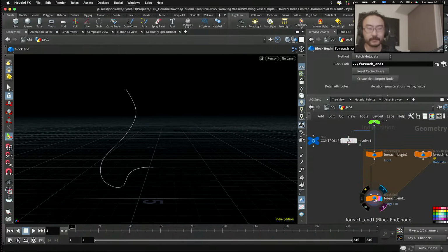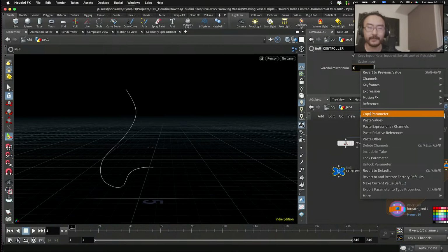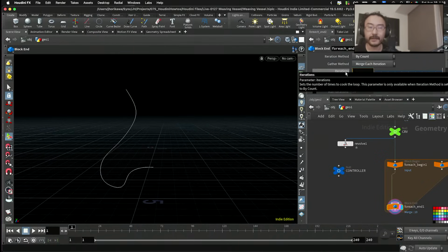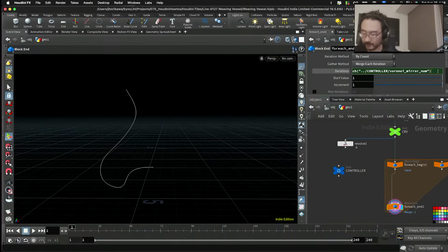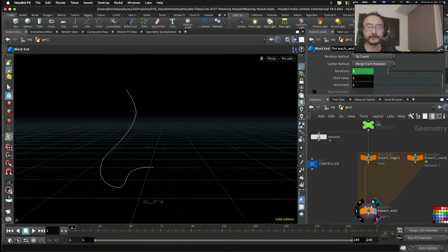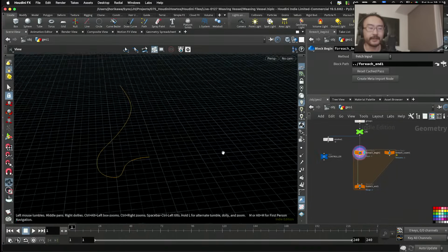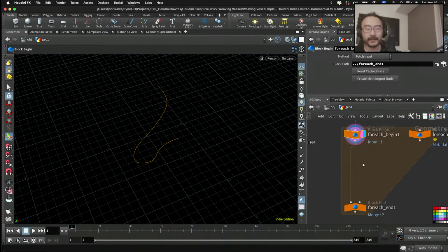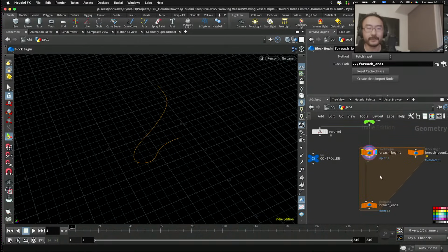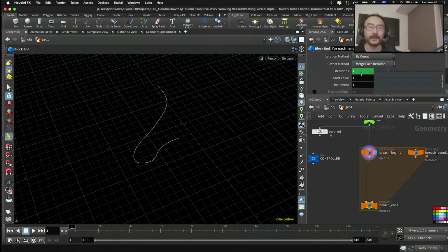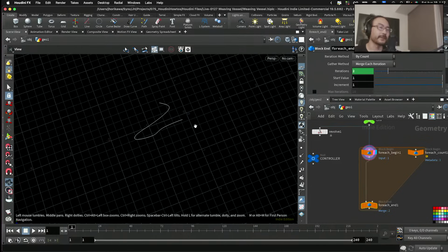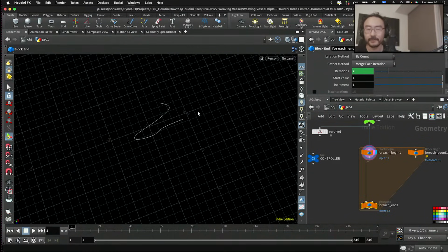Okay, now I'm going to copy this value here, paste it to the iteration here, multiply by 2 so that I'll have two surfaces. I can create two surfaces in here. Right. Now, first thing I'm going to do is to create a revolved surface from this curve inside here with an amount of angle which is divided by the whole loop number. So in this case, the revolved geometry has 360 degrees as a total. So if you divide it by 2, one surface has 180 degrees.